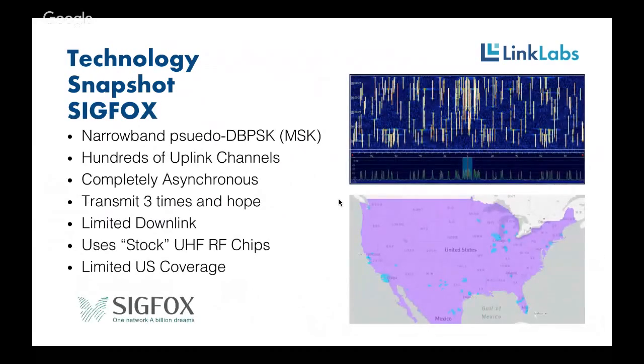Sigfox, this industry is a pretty young one, but this is really the granddaddy of technologies that got a lot of interest started here. Sigfox is a very, very simple system where devices transmit a simple, small 10 or 12 byte message 3 times and just hope that the base station receives it. This is a spectrograph showing a number of Sigfox messages being transmitted simultaneously.